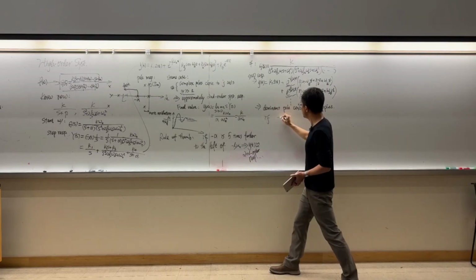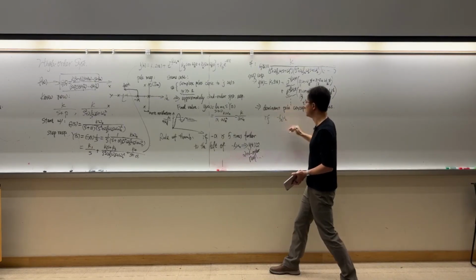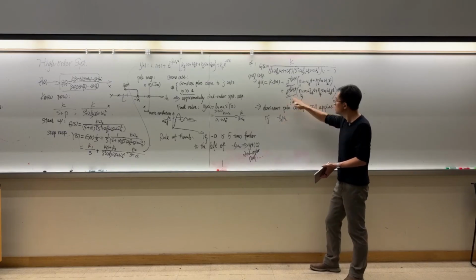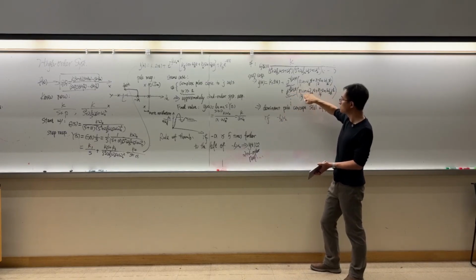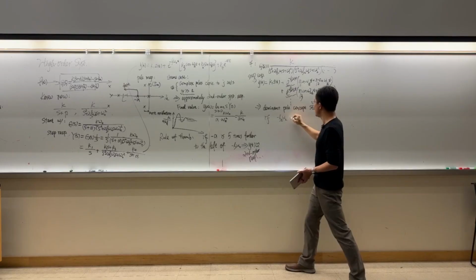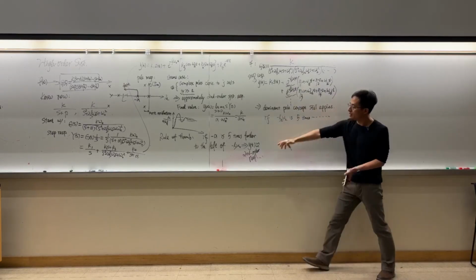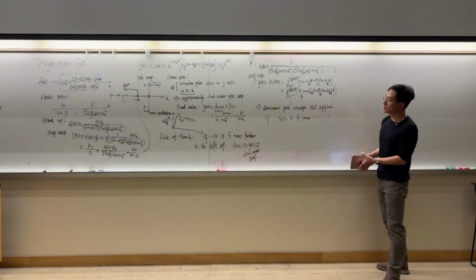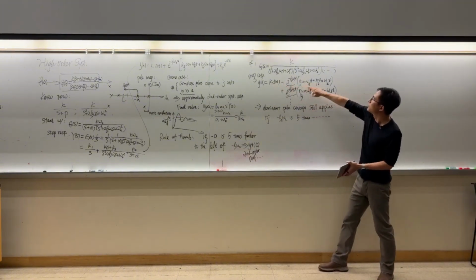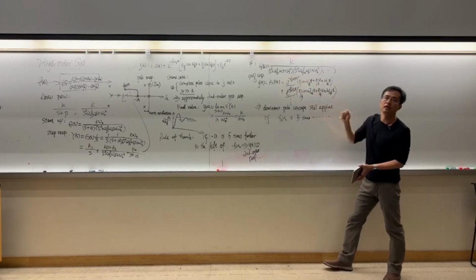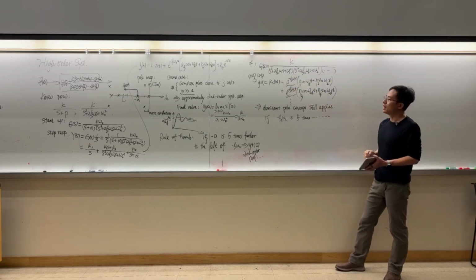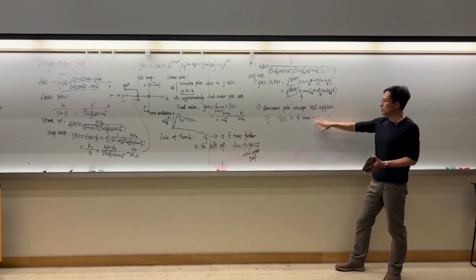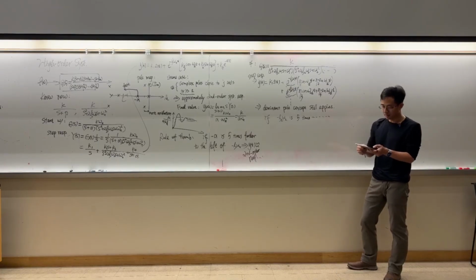If negative zeta 2 omega 2, the real part of the complex poles here, is 5 times further to the left of the first dominant pole, then you can regard the first dominant pole as governing the response, especially at the steady state value. You can finish the writing of this part; I'll just verbally explain. The concept is exactly the same.